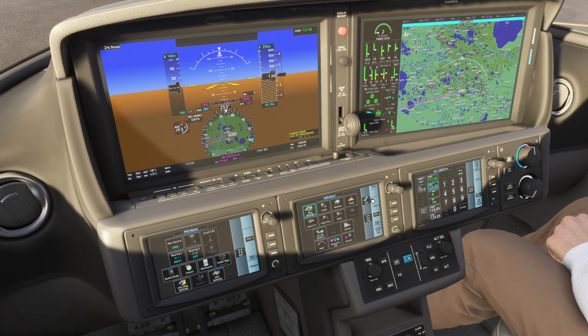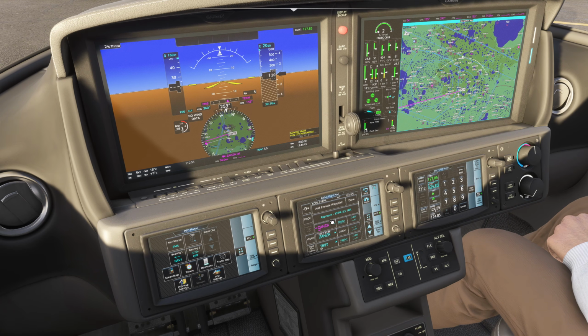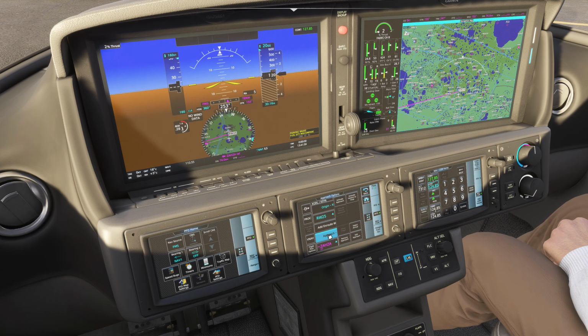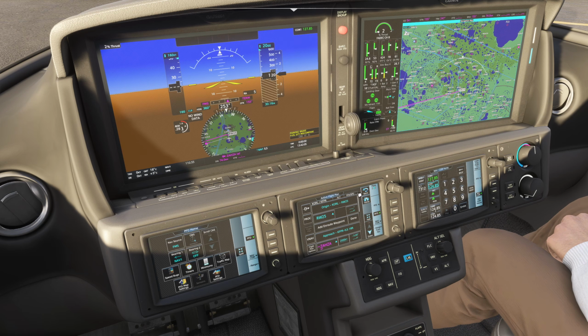And we can see our flight plan by going to Home, Flight Plan, and all our altitudes are all here. So if we want to follow the VNAV down to our approach, it will take us here to 2,000. We want to select our approach to make sure we have the right ILS 10 right approach here. We don't want to activate until we get closer to the Zaza waypoint.